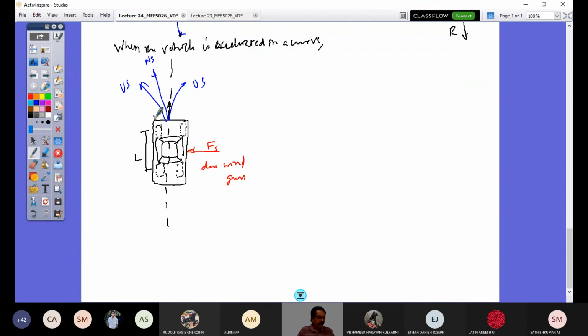Right? Can you find out the V characteristic speed and V critical speed? How do you get it? What is the value of this? We said that delta F requirement should be equal to 2 times L by R for a neutral steer effect, and here delta F requirement becomes 0.